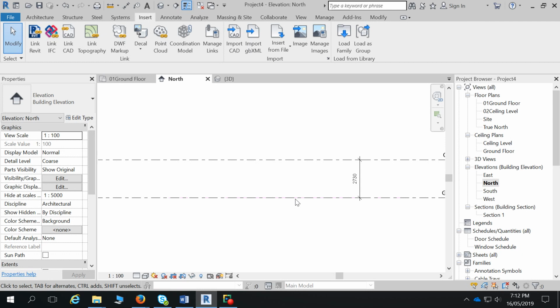So has everyone got that in? So you just want magenta or something like that. If you give it to your ground floor plan, it won't apply it to any other view. So it's overriding the graphics in that view only, not in anything else. So if you go back to your overriding ground floor, you can go to visibility graphics and override it. So go to import categories.